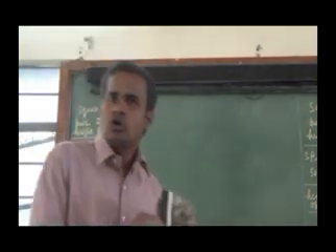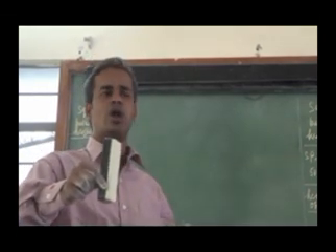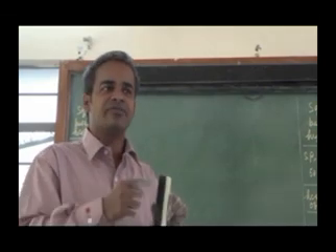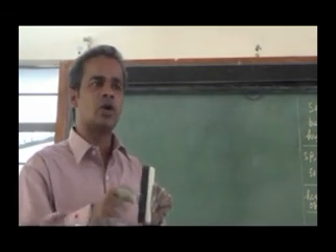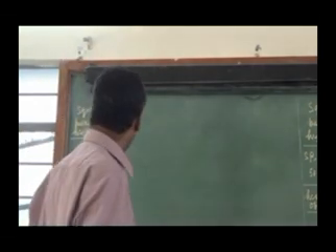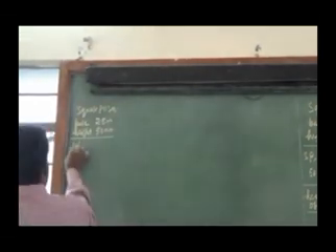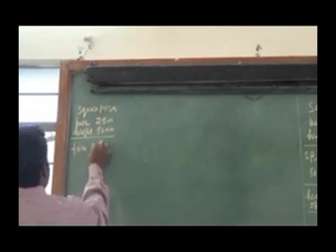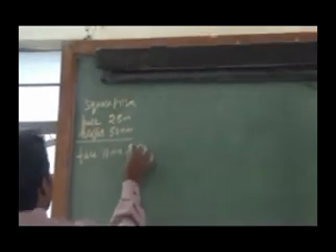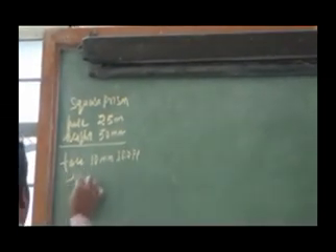You see here, the whole object is not in front of the picture plane. What is in front of it? The face which is parallel, that face alone is 10 mm in front of it. Right? So the face is 10 mm in front of the picture plane, parallel.